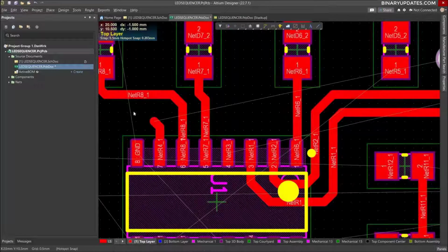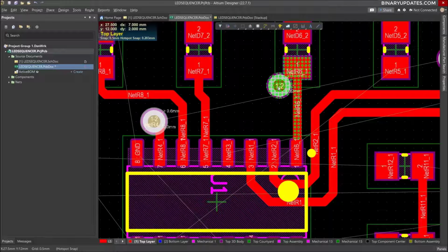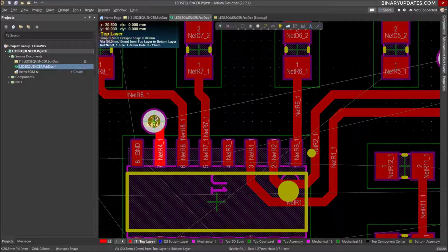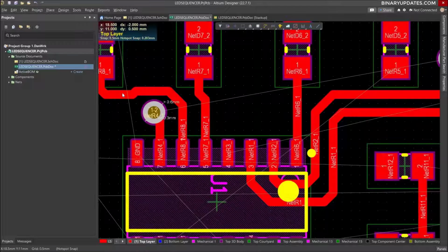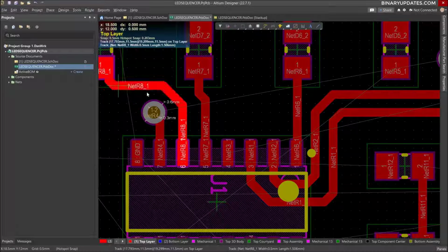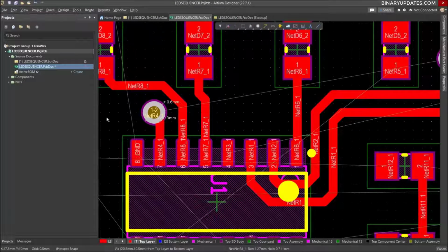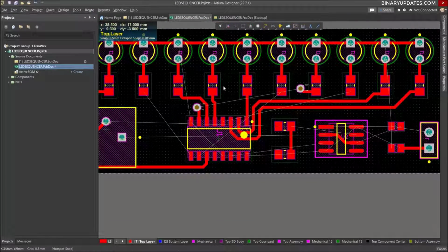So this is the advantage of doing manual routing. You can have your personal preferences for how you place your components. So now I select the vias, and now I place them, and now they don't connect to the top of the track, right? So now there's no problem. If you want, you can move this via a little bit, but it may not be needed, or it may be needed. It just depends, right? You can just move it like this. So this is how I would keep the connections.